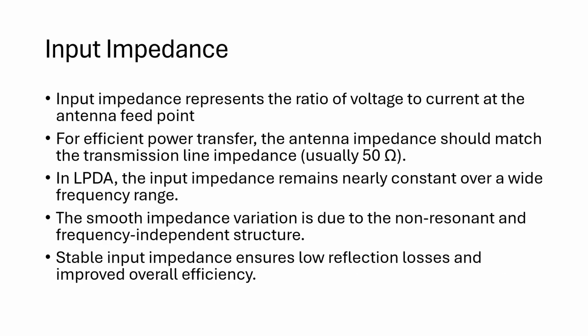Now we are going to discuss input impedance. The input impedance represents the ratio of voltage to current at the feed point. For efficient power transfer, it should match the transmission line impedance, typically 50 ohms. In our design, the input impedance remains nearly constant across the operating range, ensuring minimum reflection loss.